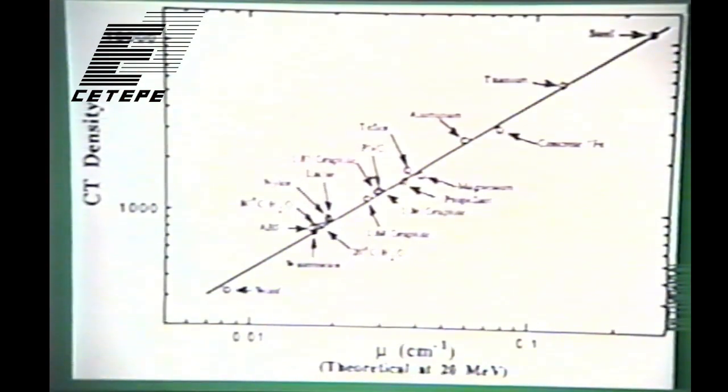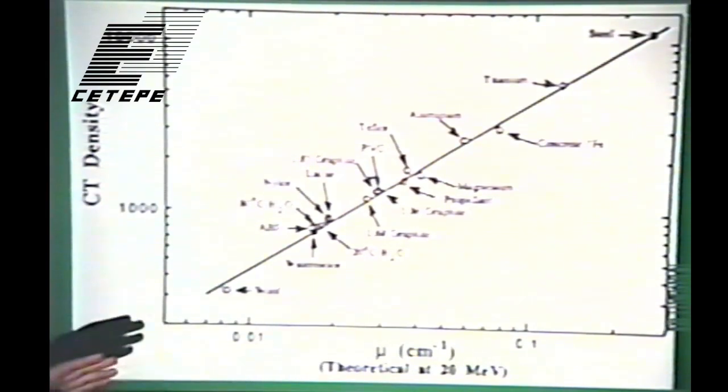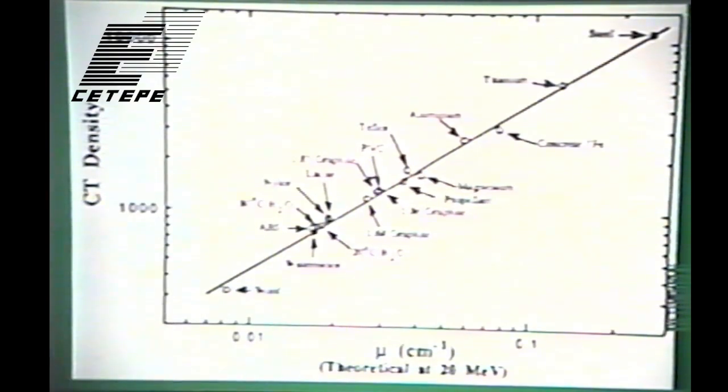I don't know why this is in here, except that in the area of non-destructive testing, they don't just utilize the diagnostic energy range. This is for 20 MeV photons. What you'd have here would be an electron impact X-ray source, very much like what we talked about, except that the means utilized to blast the electrons into the anode would be what's called a LINAC, or a linear accelerator. Okay, so this is a massive machine to achieve these huge energies, not just a little X-ray tube.